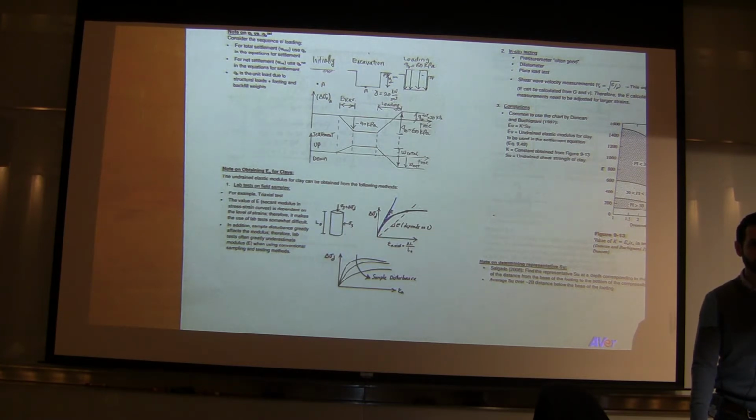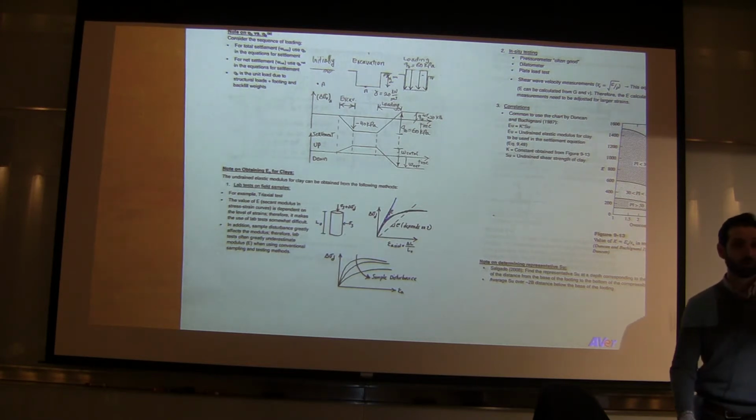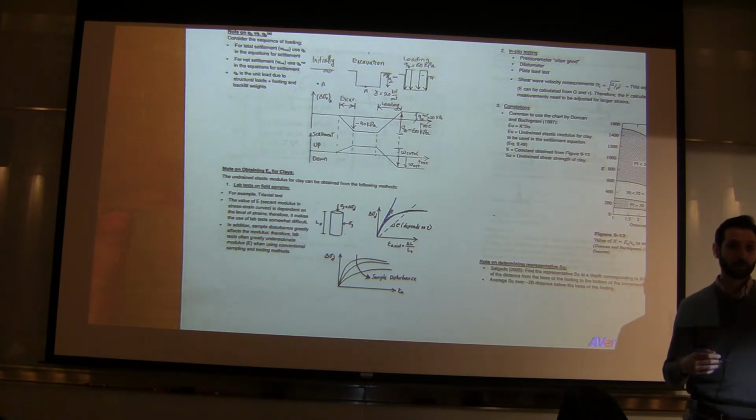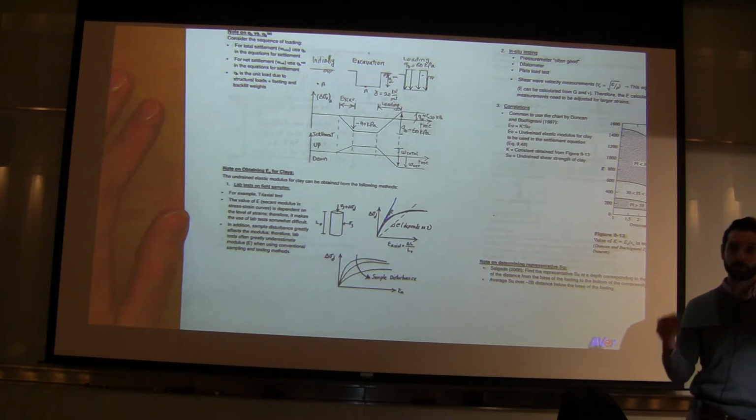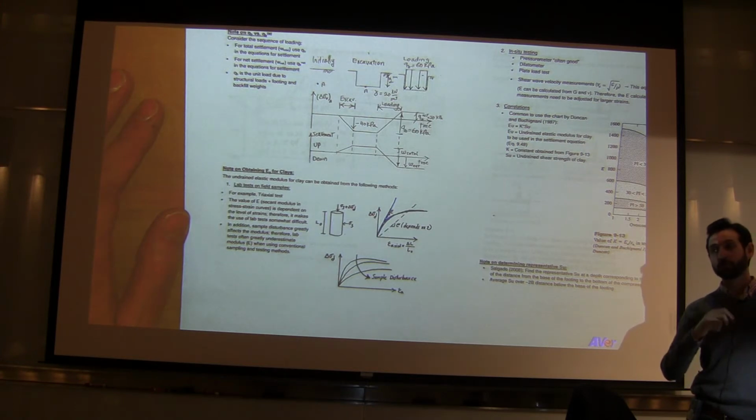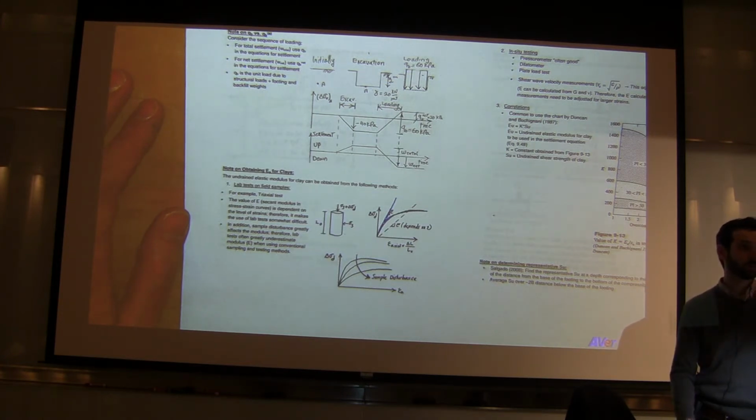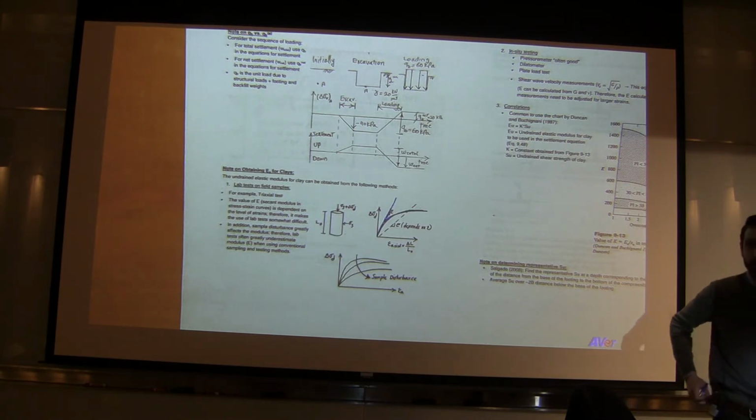You modify it by some factor. Exactly. You apply some factor of safety and reduce and increase the elastic modulus. The art of doing that is to know how much you have to modify, and that's the experience that you gain, or the more experienced practitioners can tell you how much off you could be in terms of elastic modulus. But let's say you have 100 kPa, maybe you reduce it by 50% and you plug in 50 kPa, and 150 kPa. So you go 50% higher and 50% lower, and then you do your calculation based on that, and you give a range of settlements to the designers, the structural engineers.